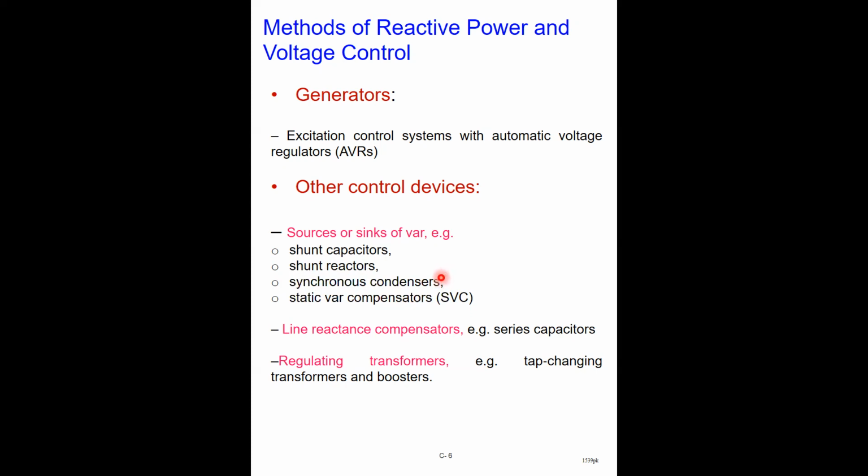Have you heard of synchronous condenser? What is this? Because condenser, I've heard of capacitor, but here they have the term synchronous. I think it's a generator that is operated to only supply and receive reactive power, right? But it's not a generator, it's a synchronous motor. So it will not be the traditional conventional synchronous motor, but it has to be specifically designed for compensation purpose.